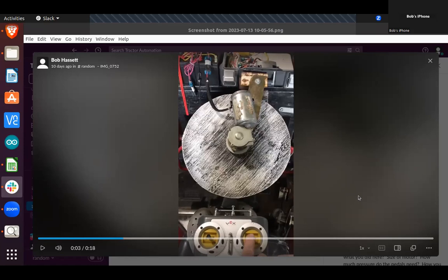It's held by 3 pegs, and sometimes that motor will jump up and out of the socket. So I'm going to have to put longer pegs in, and I don't see that's a problem because I can tap that and put them in longer, and there's plenty of space under the plywood before it hits anything on the steering wheel.